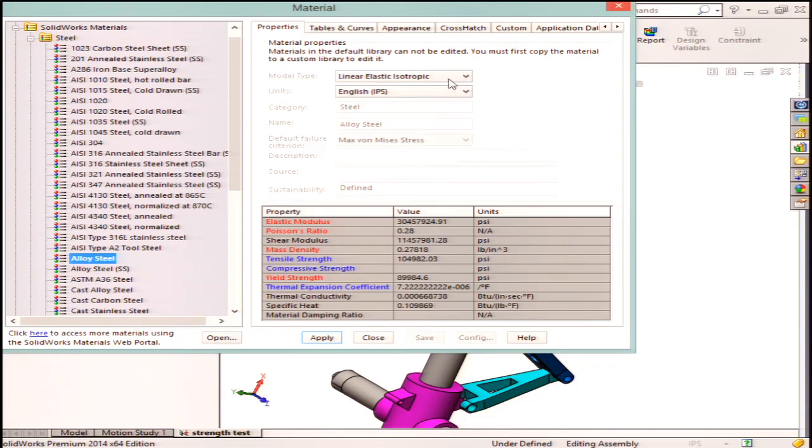So here, you can choose the material model that you're going to use. Remember I said we're going to stay on that line, that linear elastic region? So that's the model type we're going to choose. If we had chosen a nonlinear study, if I were to click this box, here I only have 2 options, just 2 different variations of linear elastic. One is isotropic, one is orthotropic, or some people might call that anisotropic. It's basically just like wood. You pull on it one way, it's fine. If you go with the grain or against the grain, it's stronger or weaker in different directions. If I were doing a nonlinear study, I would have a dozen or so different material types, material models I can choose, whether it's hyperelastic or something like nitinol, shape memory alloys, all these different material models I can choose.